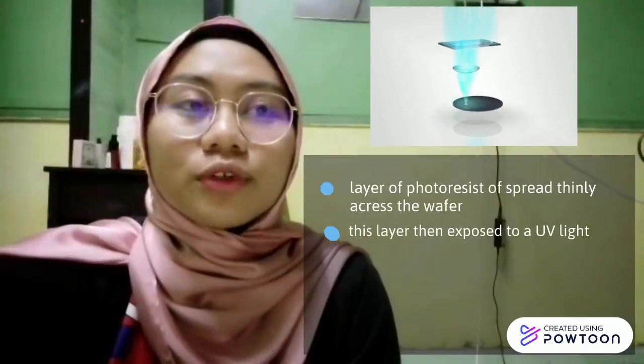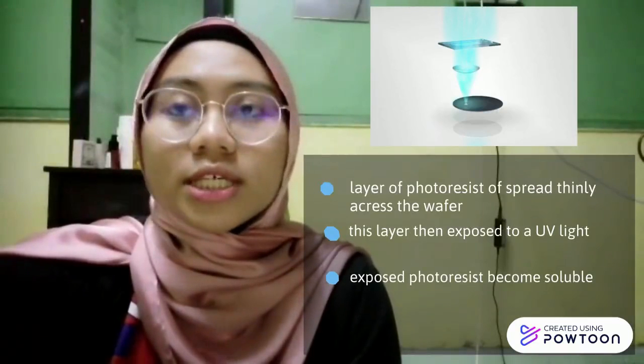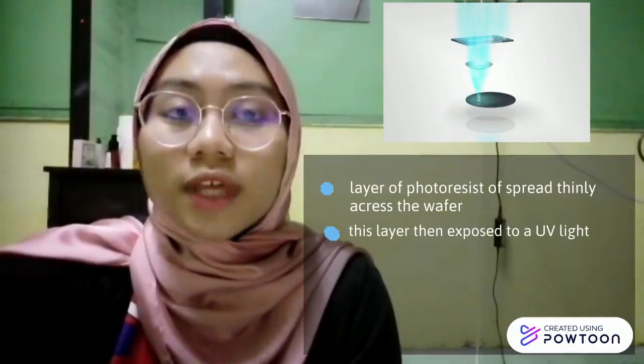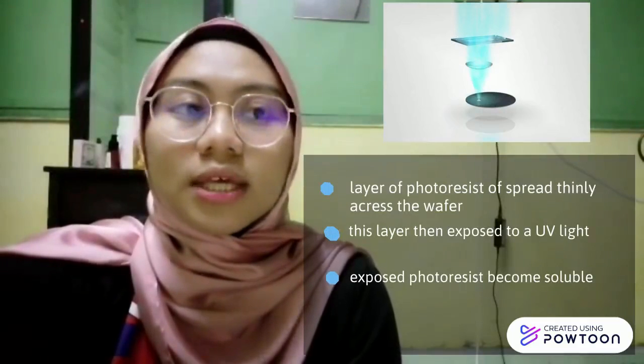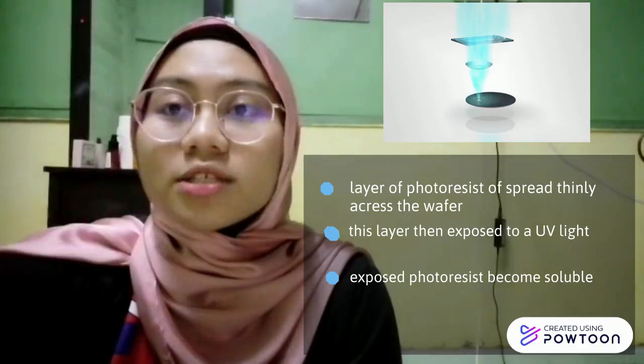Next, we go to the photolithography step. After being polished and prepared for the process, a layer of photoresist is spread thinly across the wafer. This layer is then exposed to a UV light mask, which is shaped in the pattern of the microprocessor circuits. Exposed photoresist becomes soluble and is washed off by a solvent.